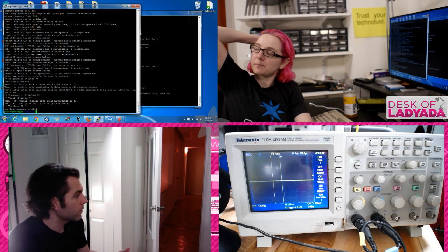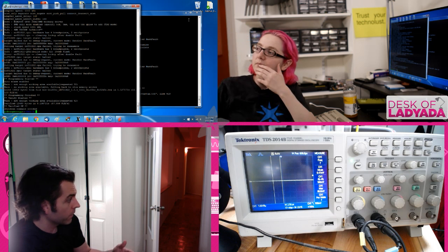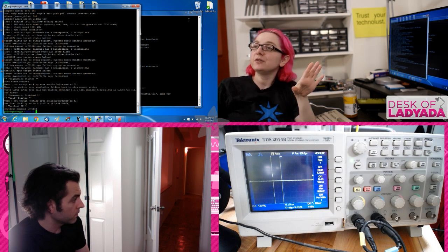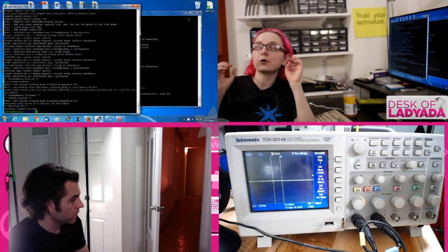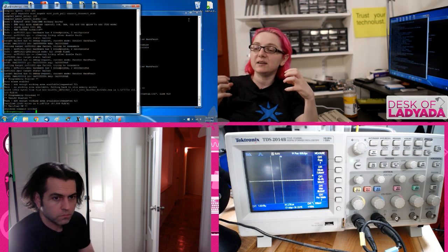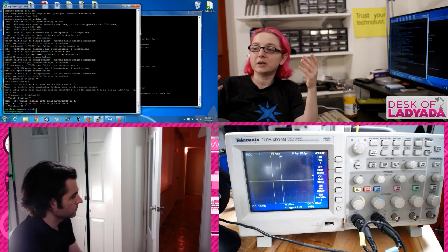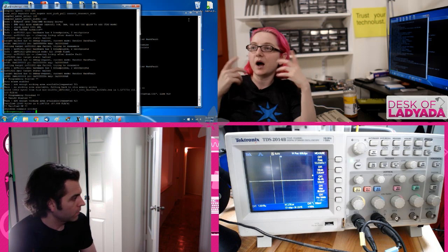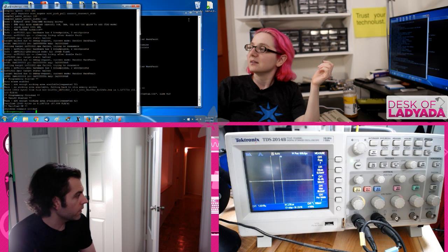So the way you discovered this was you started poking around in the kernel that the Raspberry Pi uses. No, I actually didn't have to do any of that. Somebody already did it. I was steeling myself for, okay, I'm going to add native GPIO bit-bang support to OpenOCD, but then I downloaded it and I noticed that somebody had already added it as an option. I was like, that's neat. It's already done. So that's one of the neat things about open source.